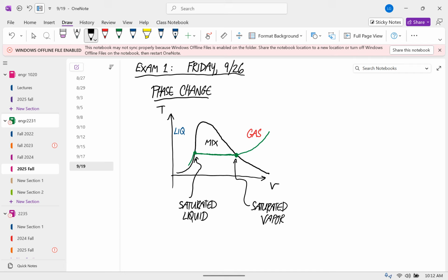So I'm just asking to confirm, the y-axis is temperature and the x-axis is specific volume, right? Correct. So it gets to a certain temperature and then goes along a horizontal line, in which the specific volume is increasing. Then both temperature and volume increase. And so while something's undergoing a phase change with a constant pressure, the temperature does not go up at all. So this is for a low pressure.